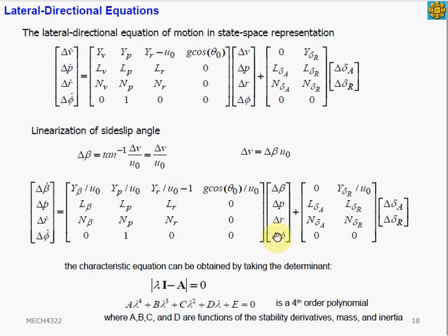This means that we're going to drop the roll rate and the roll angle for our spiral approximation, although we know that in spiral mode the aircraft actually goes through changes in the roll angle as well. We can retain this variable if we want to make a 2 degree of freedom approximation, but in the textbook example it is deriving a 1 degree of freedom approximation of the spiral mode.